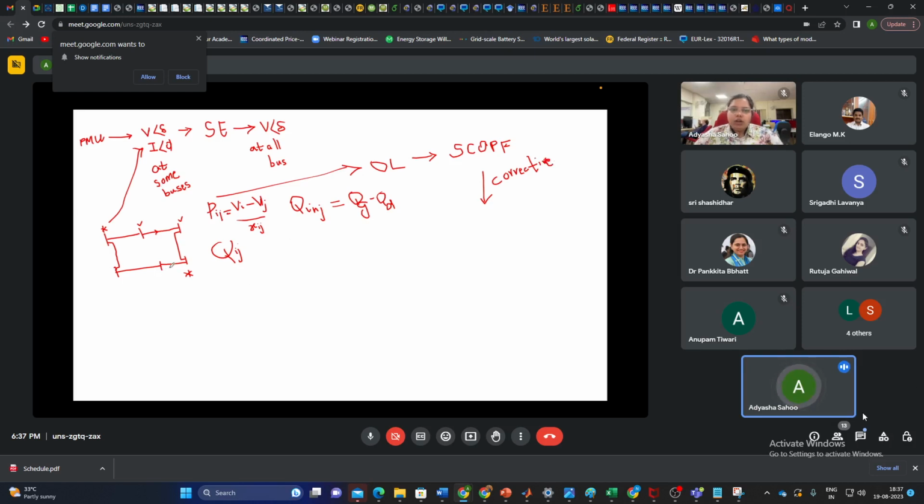Or let's say you had a huge load here, P load, and it became zero. So under this case, what rescheduling you have to do, right? Reschedule the generator, and for that you can do economic dispatch or optimal power flow. So I hope this is clear. So these are the kinds of studies that you can do utilizing the data that is being made available by the PMUs.